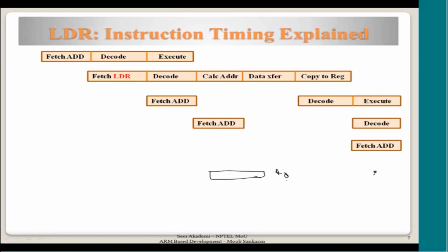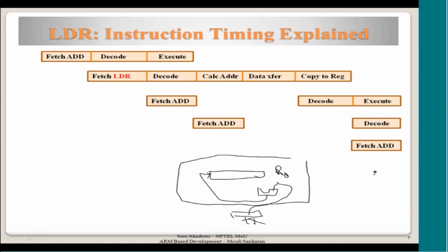The memory cycle has happened and the data in register has got the data from the memory. Now this has to be moved through the path going through the ALU, then the barrel shifter, and then the register file, where it has to get written into RD. So this whole operation happens within the data path.